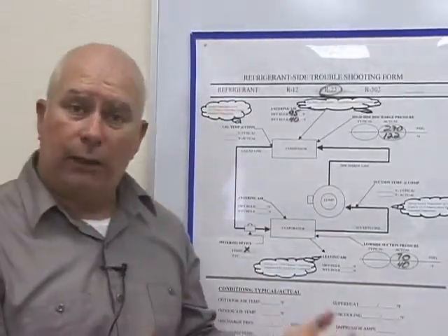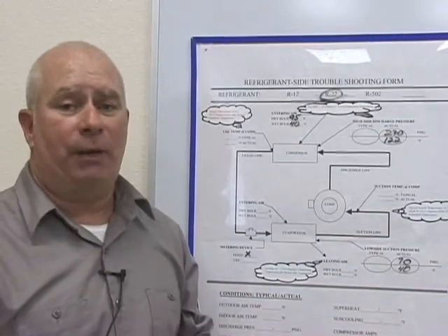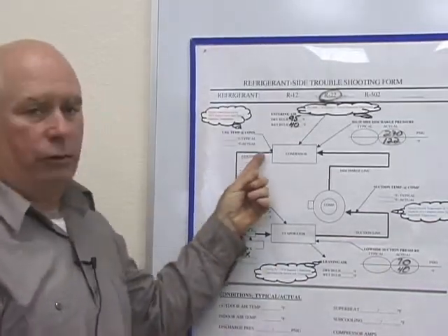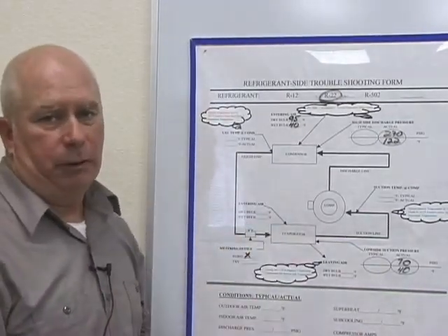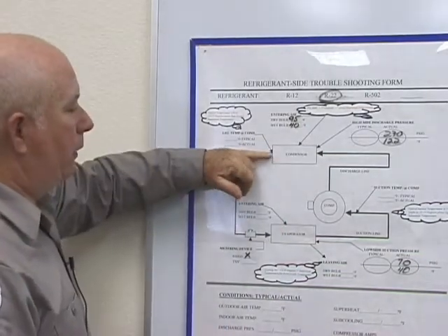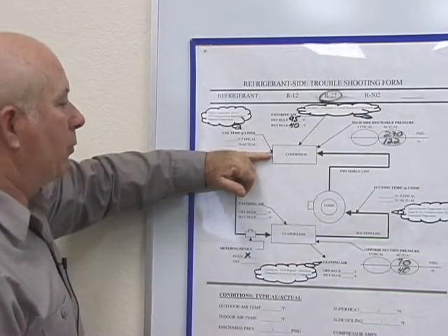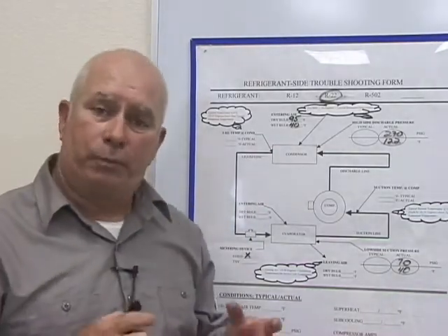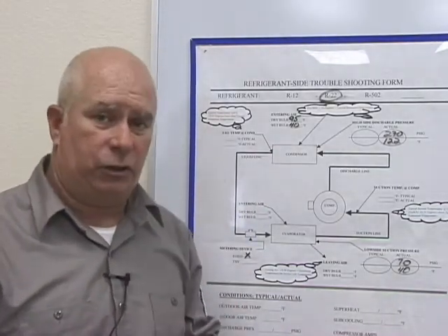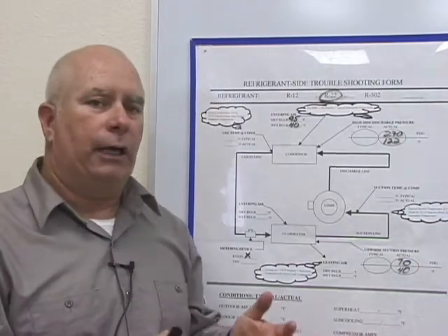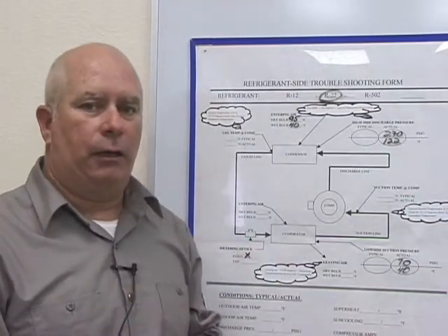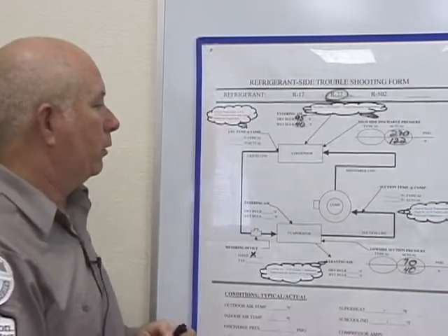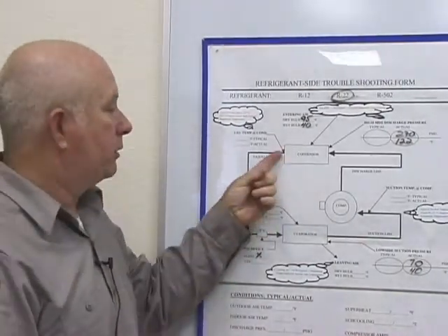The liquid temperature means just that. The liquid of that refrigerant inside that pipe. Now, we can't measure the liquid inside that pipe. But engineers have figured out that because this is copper and because you put the thermometer outside and you protect it with some sort of insulation tape, you're going to get a give or take reading pretty close to what you should be getting if you were inside that pipe.